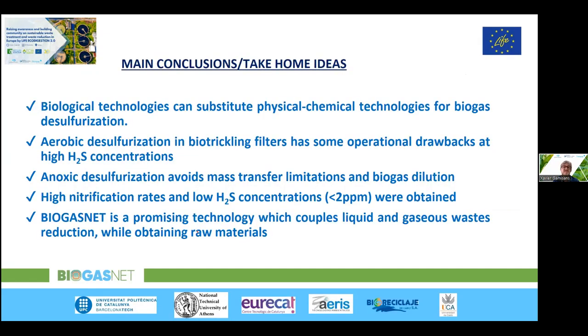Well, just some take-home ideas. For me, the most interesting thing is that the anoxic desulfurization avoids the mass transfer limitations of the aerobic process. We have reached very low H2S concentrations in biogas, and so we think that the Biogasnet technology is very promising, because it couples liquid and gaseous waste reduction while obtaining raw materials.